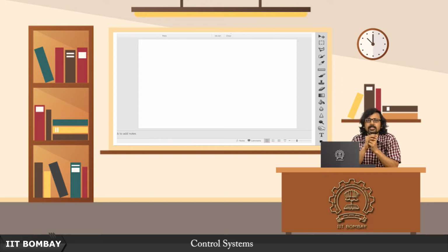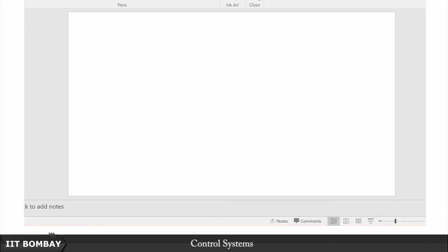And it turns out that for the SISO case, this intuition helps us quite a lot. For the MIMO case, we better be a little more careful, but for the SISO case at least, which we deal with in this course, this sort of intuition does a lot to crystallize our understanding of these concepts. So I haven't gone to the extent of taking an n cross n controllability matrix or observability matrix and finding out what its determinant is, and then showing you, for different types of structures of the A matrix, what we need for controllability and observability.